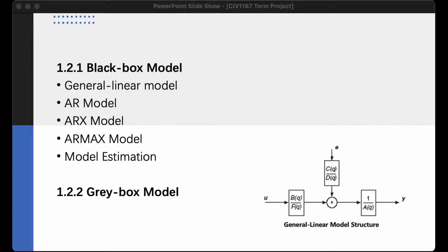Secondly, test various ARX model orders with this delay, choosing those that provide the best fit. Finally, since the ARX model describes both the system dynamics and noise properties using the same set of poles, the resulting model may be unnecessarily high in order.